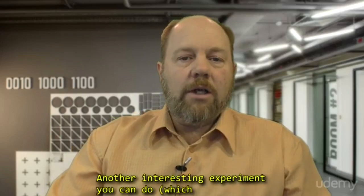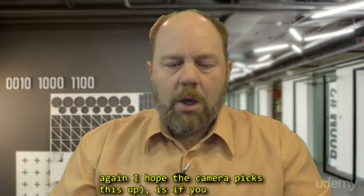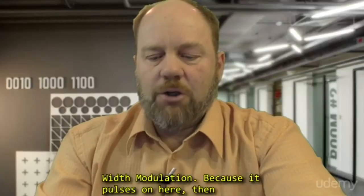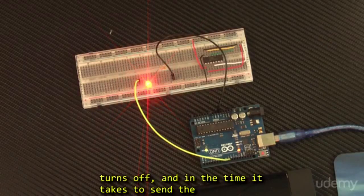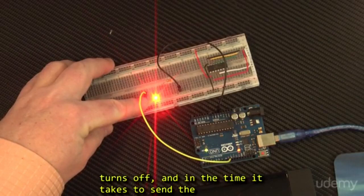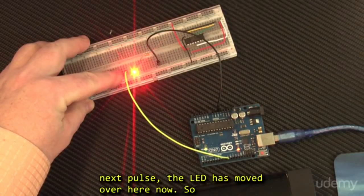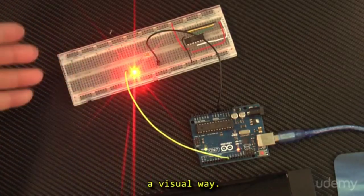Now another interesting experiment you can do, which again I hope the camera picks this up, is if you rapidly wave the LED back and forth, you can actually see the pulses of light from the pulse width modulation. Because it pulses on here and then turns off, and in the next time it takes to send the next pulse, the LED has moved over here now. So it'll really bring home the PWM that's going on in a visual way.